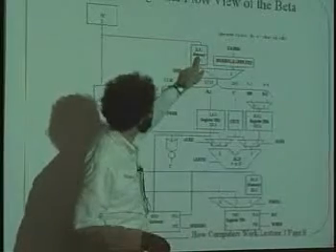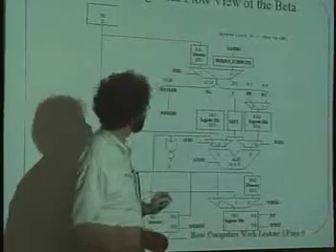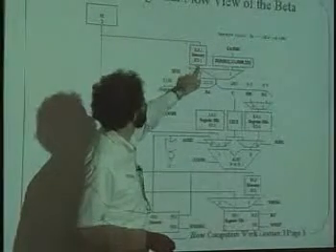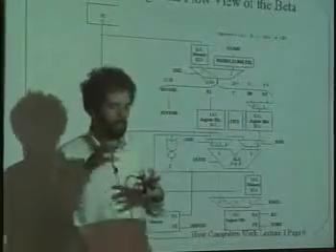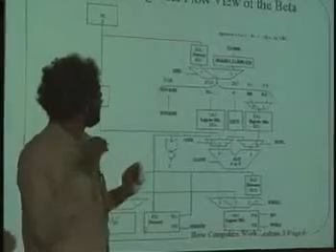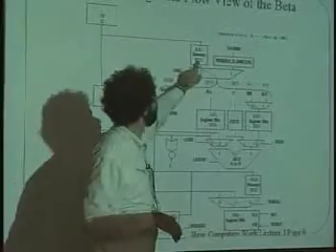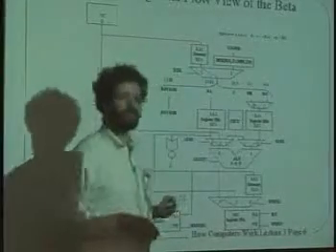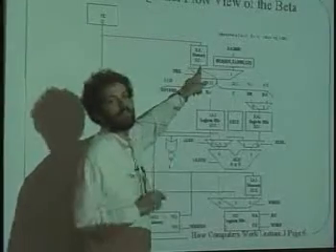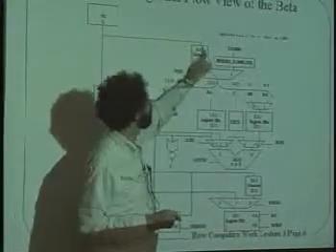And notice the memory here actually has several ports. Here's one. Read address 1 is an input here, and read data 1 is an output here. And so this is one portal to the big, slow memory. And whatever address you put in here, the memory looks up the contents of the address that you give it and spits out the data corresponding to what's at that place. So this is looking up the contents of the PC, which is being used to fetch what?